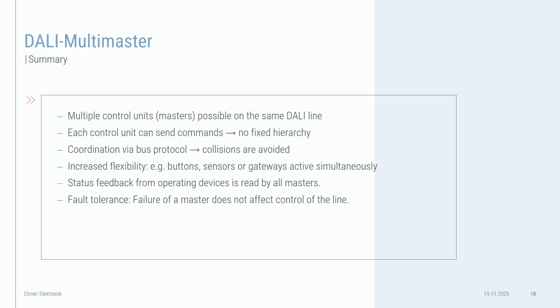A DALI multi-master is another concept. A DALI multi-master allows multiple control devices on the same line to send commands without a fixed hierarchy. The bus protocol coordinates everything to prevent collisions between those masters. So switches, sensors, and gateways can all be active at the same time.